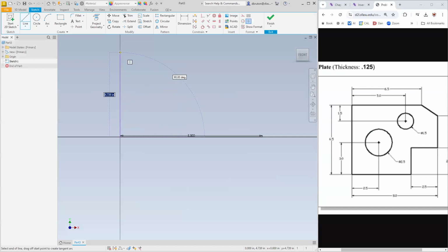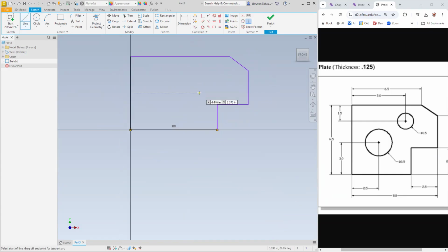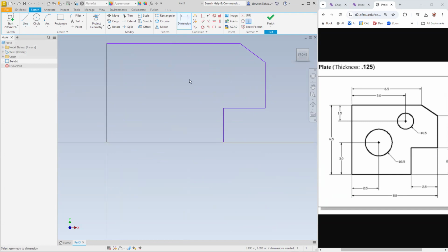That way I can come over here, do this one, horizontal, down at some angle, down here, and then in, and then back down. In fact, what I'm going to do now that I've got the general shape is delete that one and close it off right here because it is an open part until I do that. Now we can start reducing the number of unknowns. I don't really see them down at the bottom yet. Let's see. Okay, now once you click the dimension tools, it tells you that you need 7 dimensions.